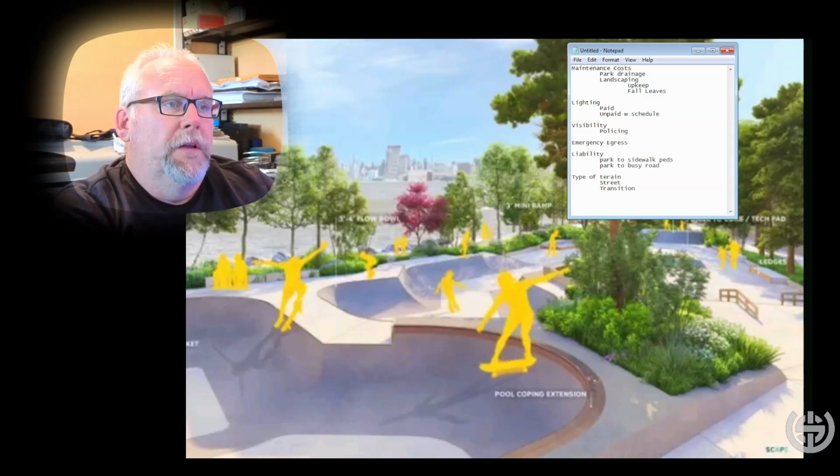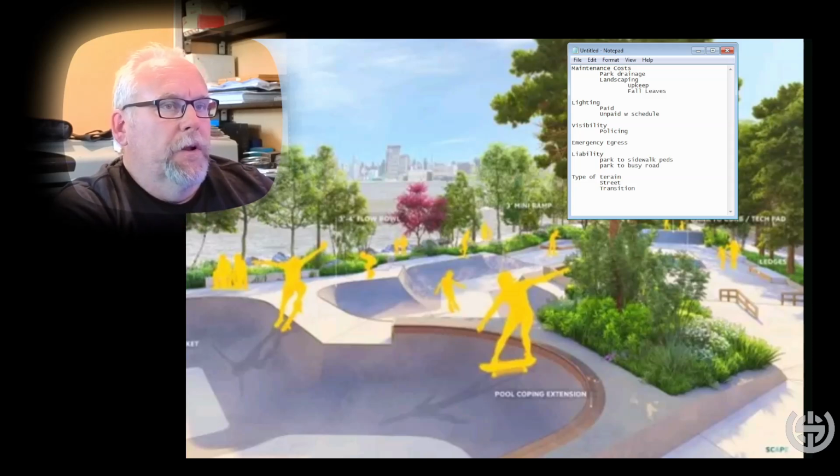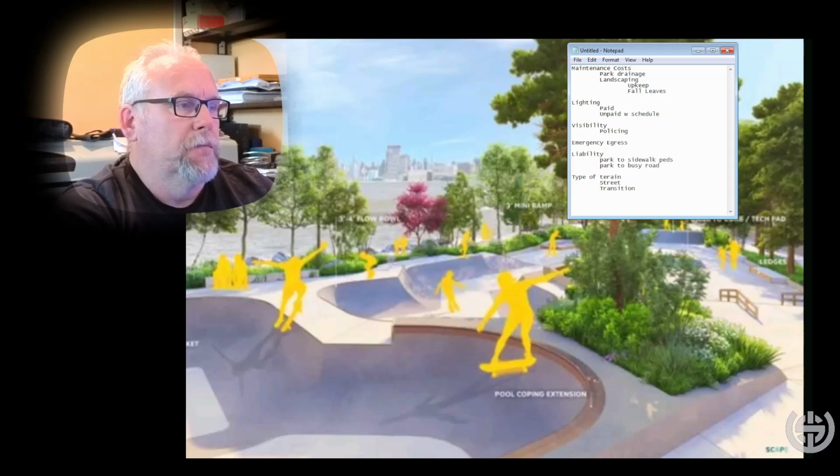And so, being next to the river, obviously, I would imagine this is classified as a floodplain. Yeah, so we're going to talk about the road that's on the right side over there. And we're going to call that ground zero or elevation zero for the sake of the conversation. The entire skate park needs to be, we'll call it Z0 plus. You really do not want flooding from the river or a lot of rain to be able to fill up any of these structures and not have adequate drainage.